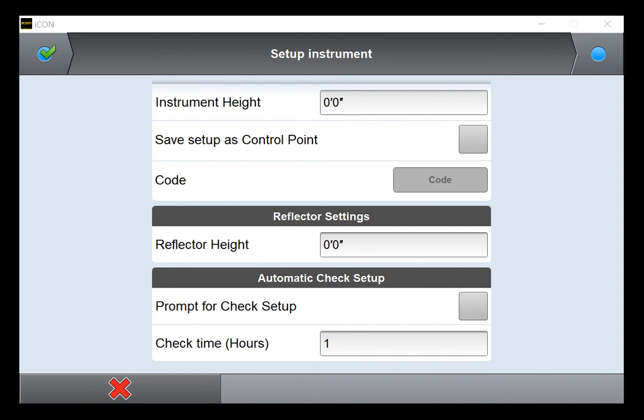What happens when a total station loses its levelness is that the center of the total station has physically moved off its axes, both vertically and horizontally. This not only affects the horizontal distances measured between points, but the angles between each point and the building as well, because the total station's base rotation angle has moved. It is very simple to avoid these errors. Just re-level your total station and complete another setup anywhere by measuring your reference targets again. You may have to do this several times throughout the course of the day, but this will absolutely save you time and money in the long run.